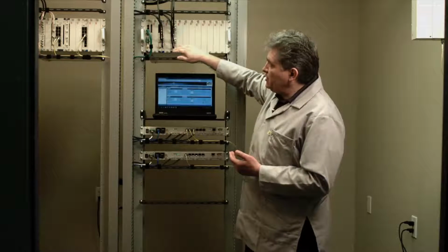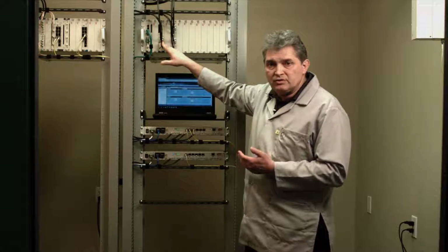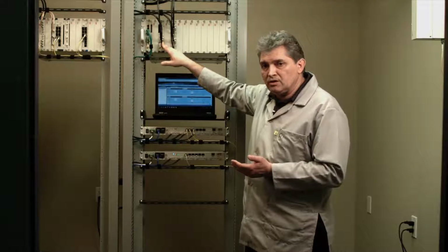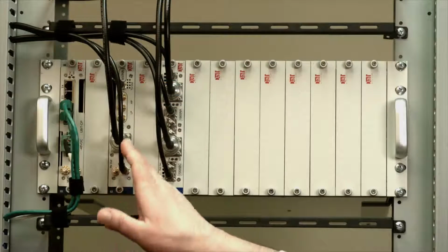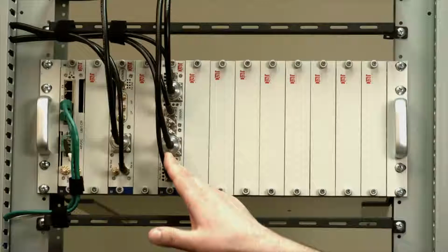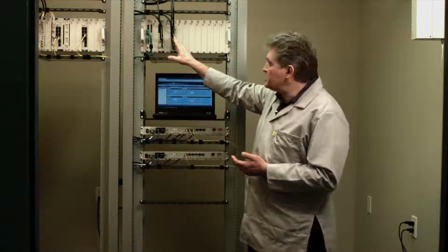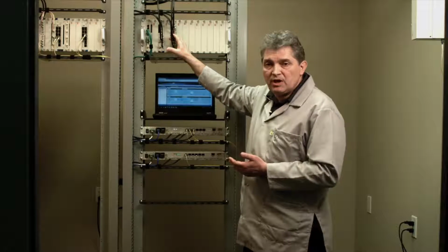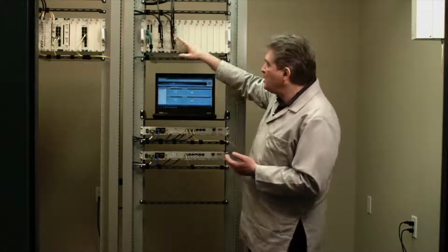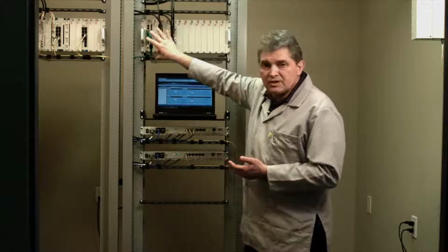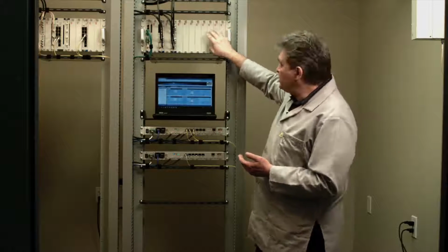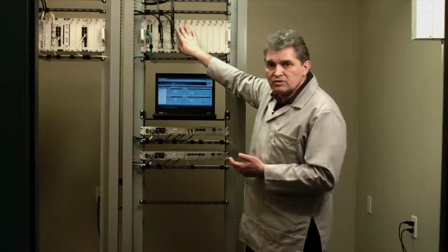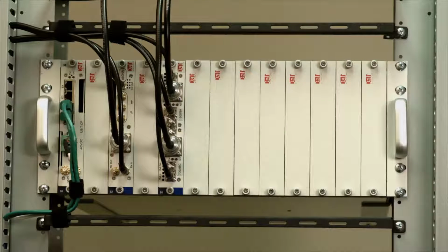So the interface unit has modules which are designed to accept downlink input power up to 100 watts, and the RFC 50 module, a dual band module that can receive power up to 37 dBm, or 5 watts. These modules are housed inside a 4RU 19-inch rack chassis, and there are 12 universal positions where different types of modules can be plugged in.